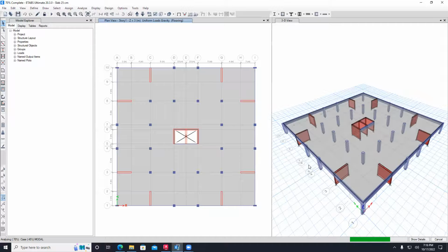So in design companies, we make 2D models to analyze the slabs and beams, and we make 3D models that have a very big mesh, maybe 2 meters or 3 meters, very, very big, because I don't care. If you make it very fine, your model will be very heavy. If you have a 60-story building and each story has a mesh of 0.5 by 0.5, your model will explode. That's why we increase the mesh size so that the model can run fast.